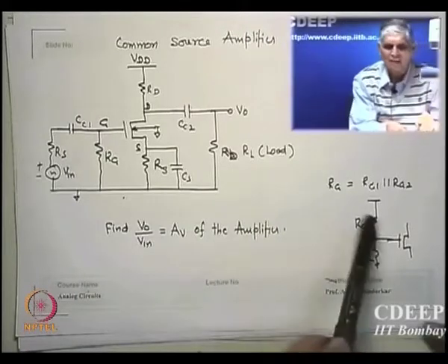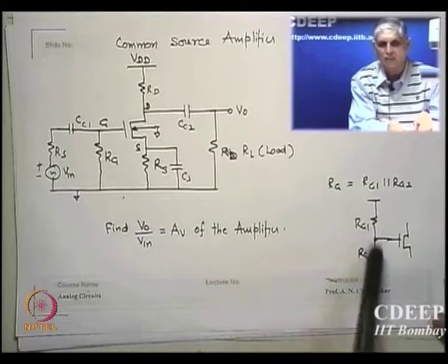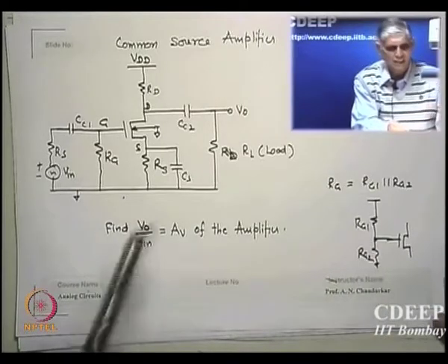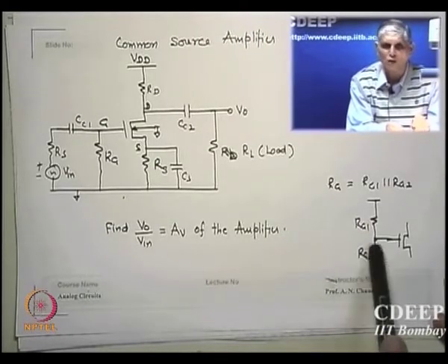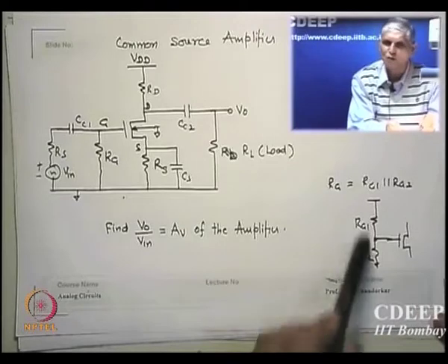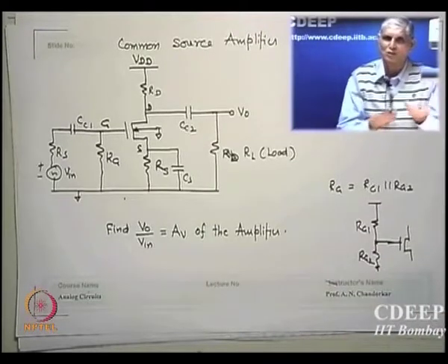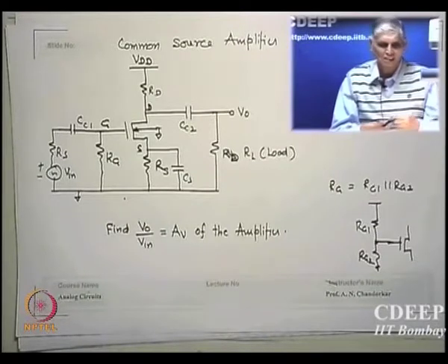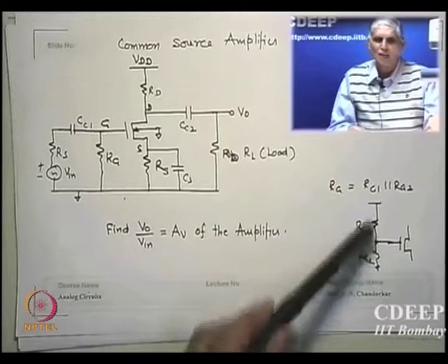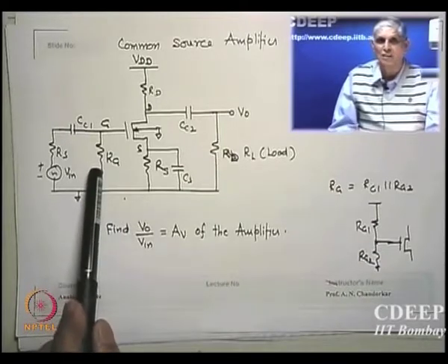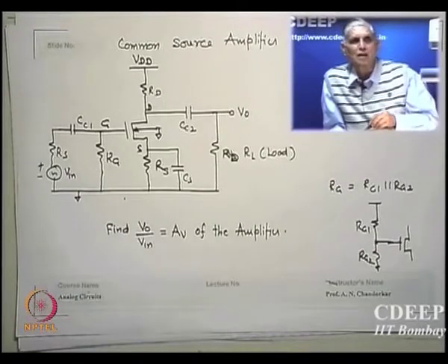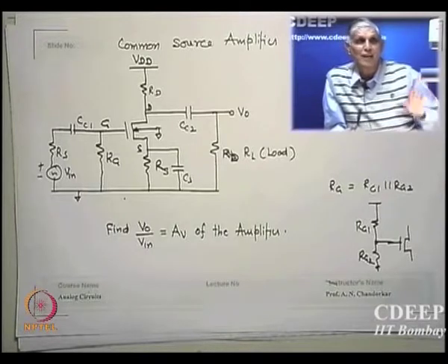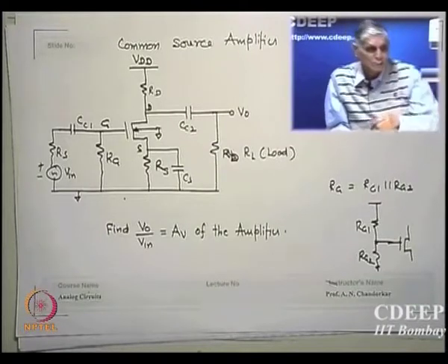Now bias is done as usual, like a fixed bias as shown here, RG1, RG2 to VDD and to the gate, and equivalent resistance is how much from Thevenin's? Please remember here it is very easy, no gate current, divider is Rg2 upon Rg1 plus Rg2 times VDD, that is your Thevenin's bias VGS you want, and how much resistance will it offer? The parallel combination, and that value I have kept here as Rg, is that correct? Rg is nothing but Rg1 parallel Rg2, is that correct? So that resistance is not shorted or opened by the capacitor, it's bias, it must sit here.